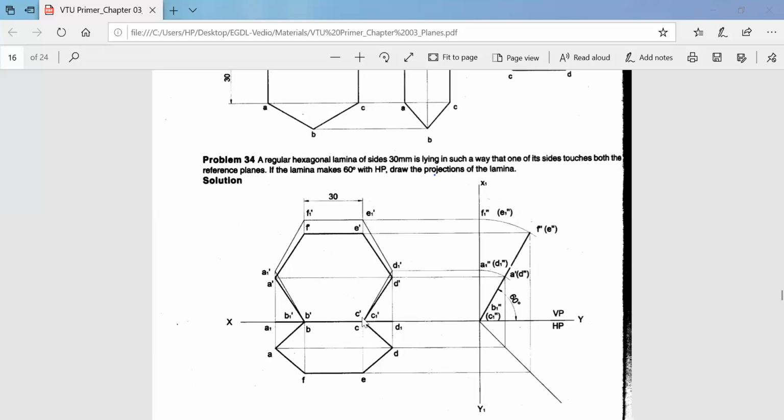So you will draw a straight line of 30 mm. After drawing the straight line of 30 mm, you will take the interior angle of 120 degrees on both sides. I am speaking about the dark line which is being drawn here. From there you take an interior angle of 120 degrees, and draw a line for the 120 degree line.